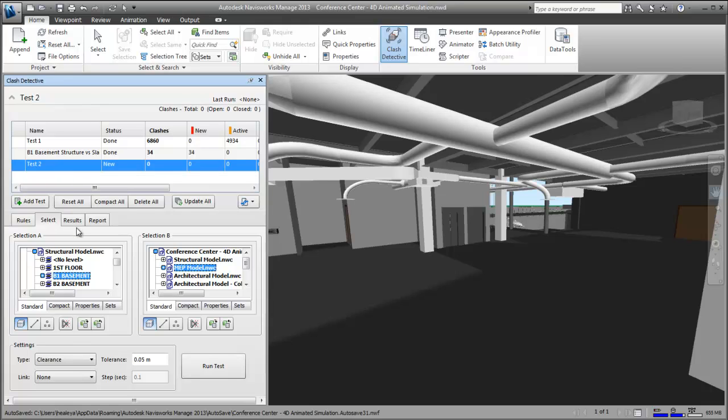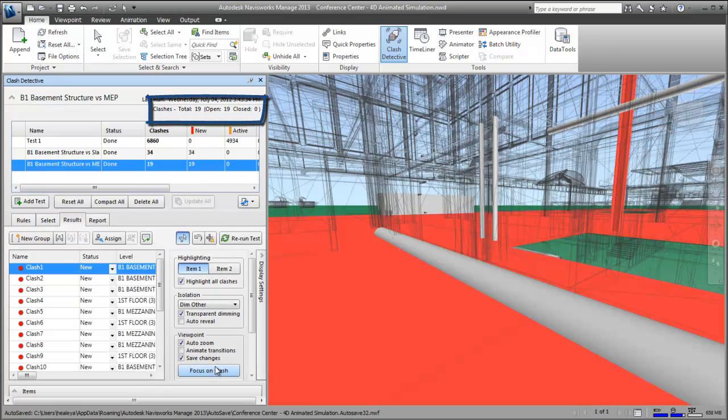Hard clashes where an actual collision has occurred will also be included in the results. Now I'll just give the test a suitable name, then click Run Test. And there, just the relevant few clashes returned. Organising my clashes like this is going to make life so much simpler. I can set up as many tests as I like and clash anything from steel girders to water coolers. Why not set up multiple clash tests yourself and explore and use the selection settings to make your own clash results more meaningful? Thanks for watching.